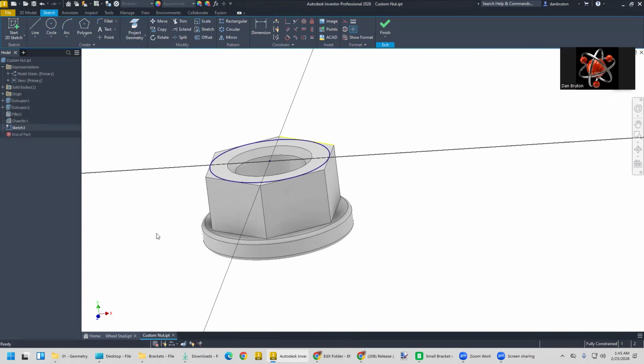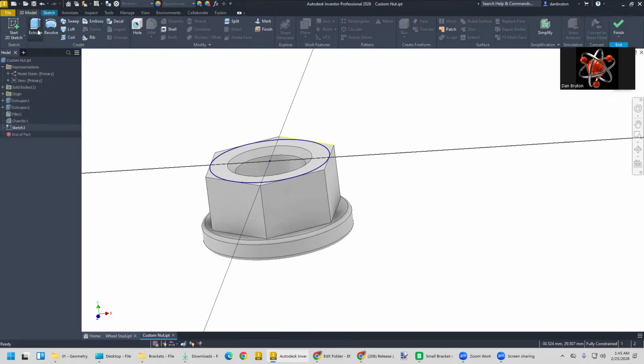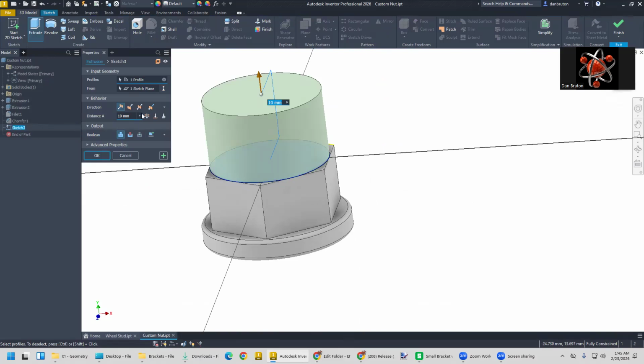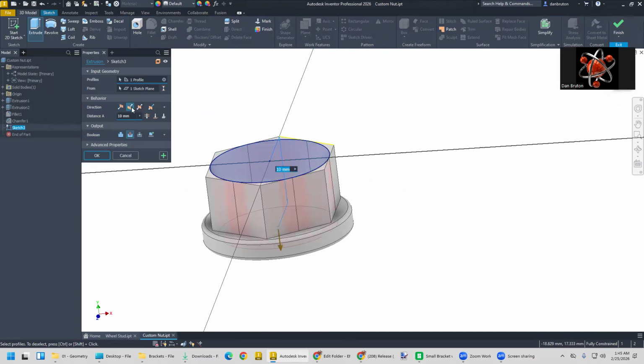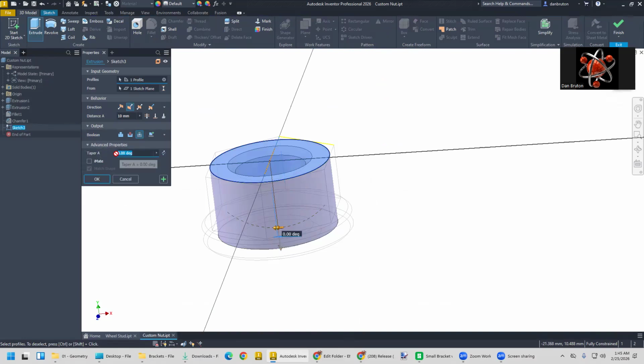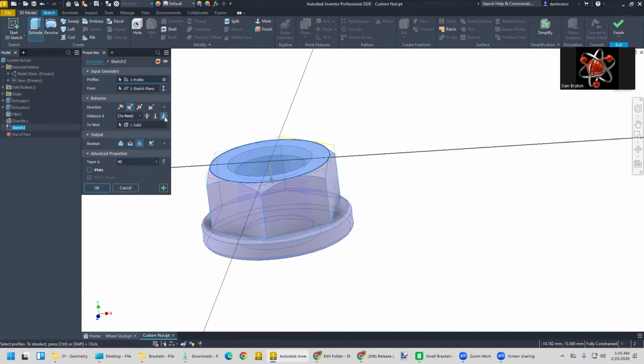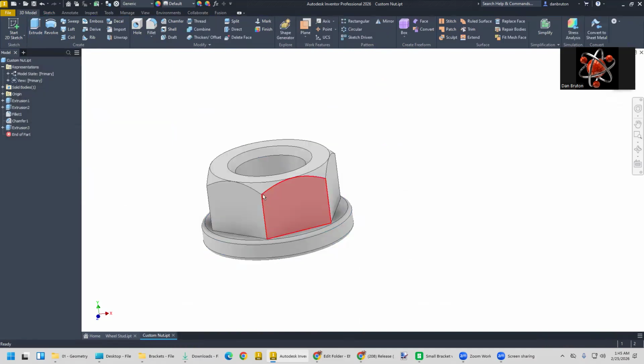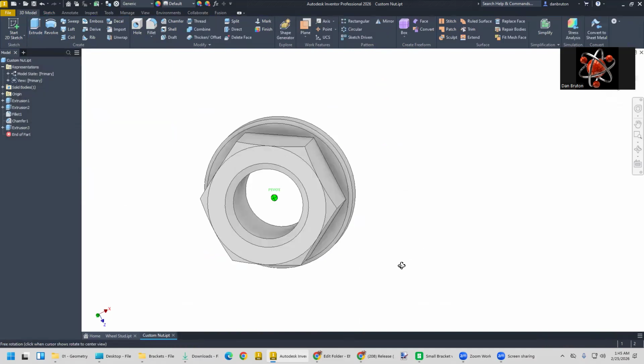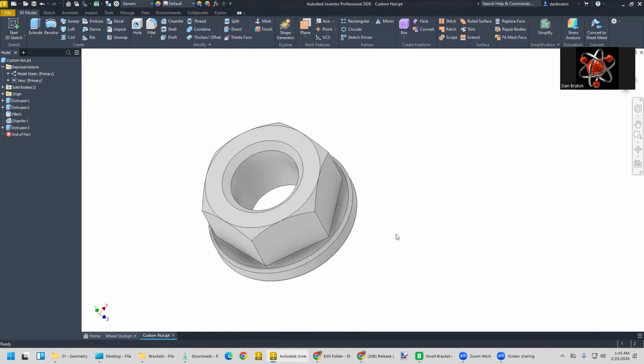And so the process we want to use here is we want to go over here to 3D model, click on extrude. We want to go down, but we don't really want to extrude. I think we want to do an intersection. And I want you to do a taper of 45 degrees. And then the other thing is you want to go on this one right here where it says to next. Okay, and then you'll see the effects of it is to give it a more realistic manufactured approach.